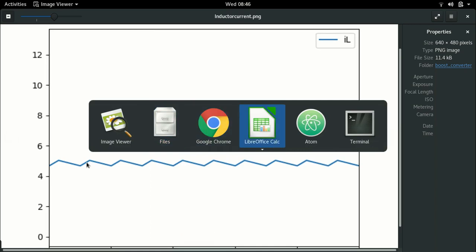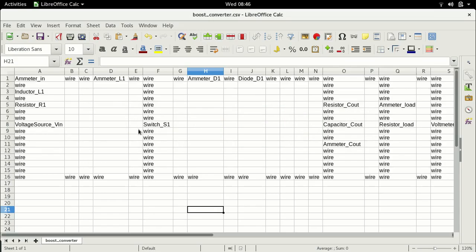Let's go back to the circuit and see when this switch is turned on. This is when the voltage source now charges the inductor through this switch, alright, because remember the current will always flow through the path of least resistance. This forward path is not the path of least resistance because there is a capacitor here, right? This switch is the path of least resistance because it's almost a short circuit. So that's why the inductor current will rise when the switch is turned on.